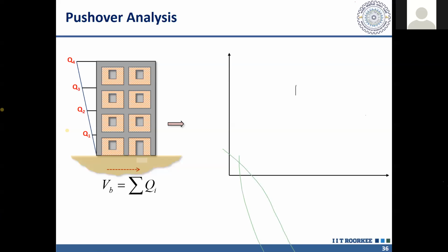Okay, so if you have plotted the bending moment diagrams for a frame under lateral load, you will see that the bending moment is maximum in the beam near the joint. Same is with columns. So the yielding will occur somewhere near the joint, but whether it will occur here or here or here, that we do not know, because it will depend upon the ratio of demand to capacity.